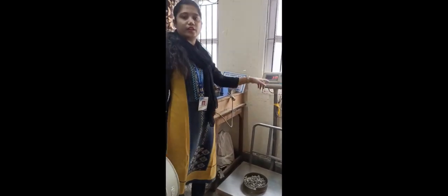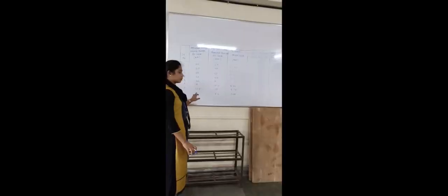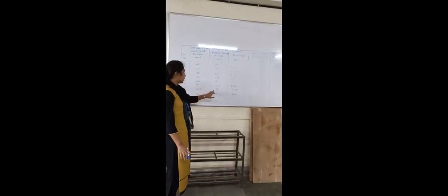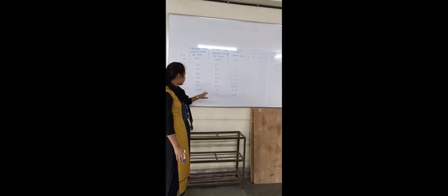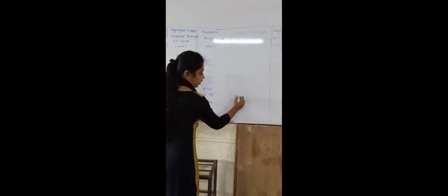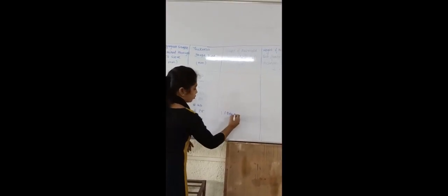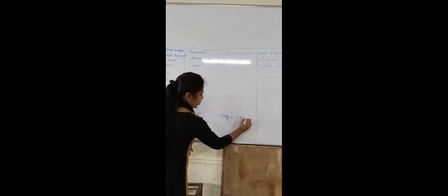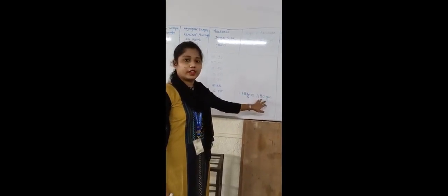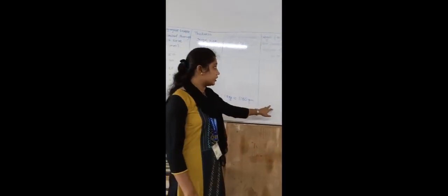Okay, 1.18 we have to convert into gram because this weight is in kg. Now we have taken the aggregate which is retained on 10 and passed by 12.5. The weight which we have taken is 1.18 kg, but we need it in gram. Multiply by 1000, we will get the reading 1180 gram. Now we will see W1.